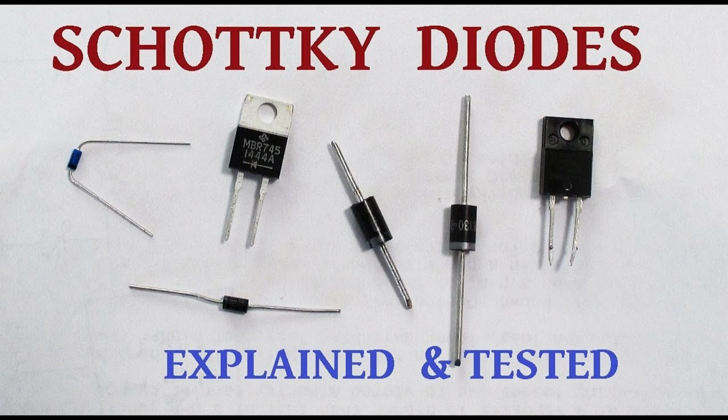Some common voltage protection techniques include fuse protection. Fuses are sacrificial devices designed to break the circuit when the current exceeds a safe threshold, protecting components from overcurrent and overvoltage conditions. Circuit breakers. Similar to fuses, circuit breakers are devices that automatically open the circuit when an overcurrent or overvoltage condition is detected. Surge protectors. Surge protectors are devices designed to divert excessive voltage spikes to the ground, protecting connected devices from voltage surges due to lightning or other sources.